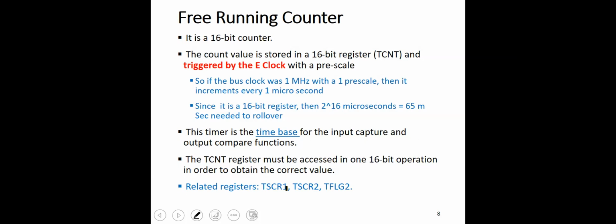For example, you can enable the timer to start counting based on some frequency, a scaled version of the e-clock. So basically there will be a maximum time. Once that maximum time is reached, when the timer overflows, then you can tell the CPU that 1 second has elapsed or one millisecond has elapsed, through interrupt or through polling. You can poll the interrupt flag of the timer overflow.